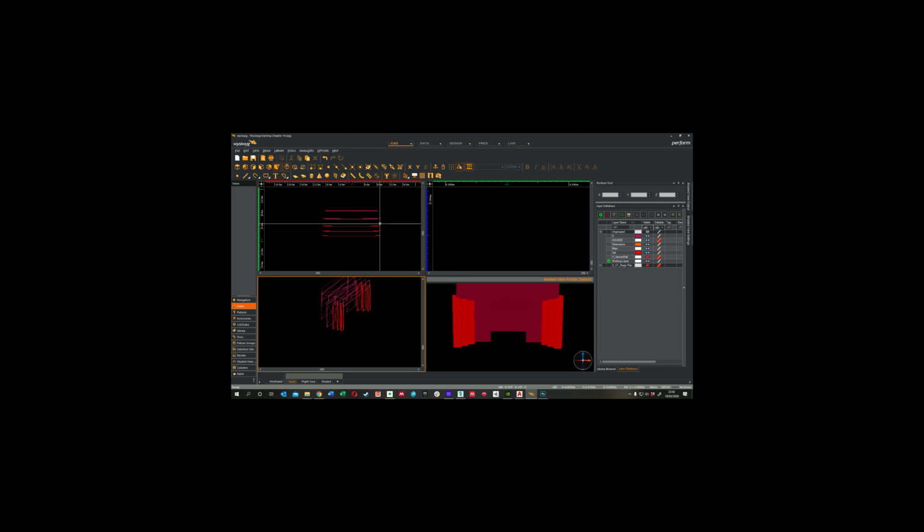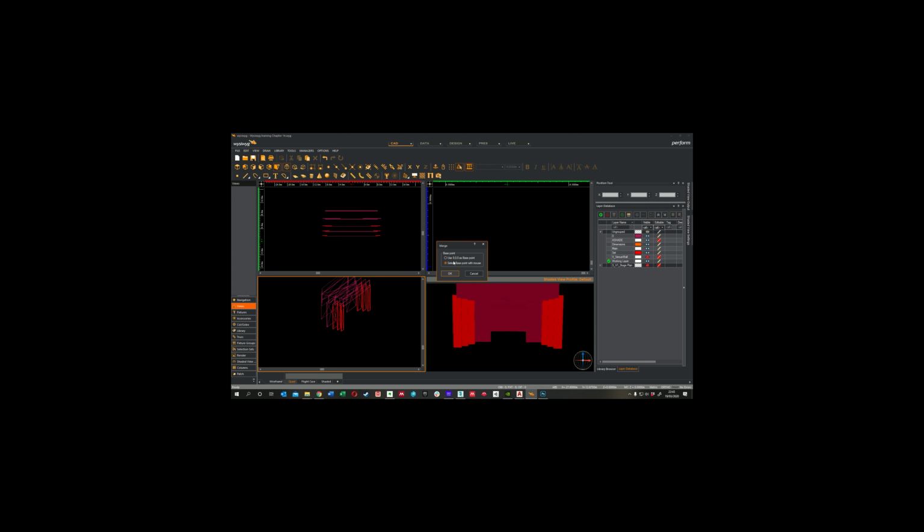So let's just go back to Wysiwyg and we'll import those FBXs. I'm just going to bring in the proscenium arch. It'll be enough just to demonstrate the point. Let's go to the proscenium, click open. It's going to bring up the merge window, which gives you the option of importing 000 or the base point. As discussed before, always use 000, even though with FBXs it doesn't actually make a lot of difference, because it kind of takes the center of the object as the center of the FBX and imports that into the 0 point. So it won't be in the position that it should be on from your plan. So it could be a bit of a waste of time, but it's just good exercise to have.